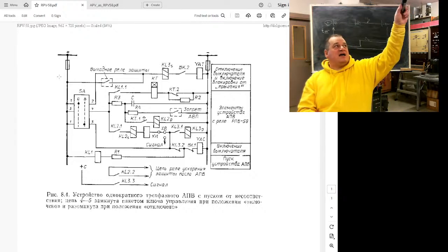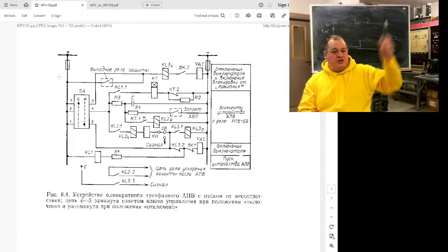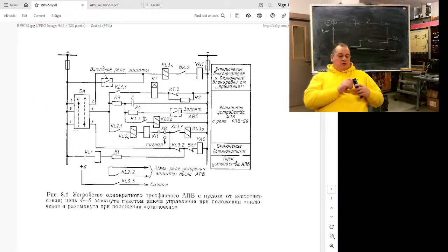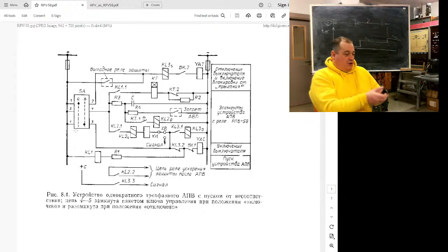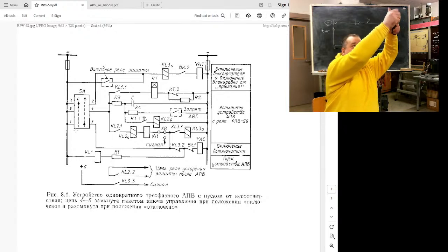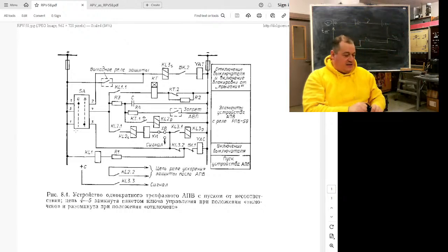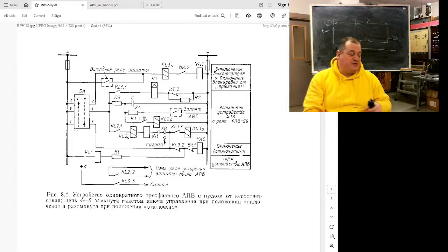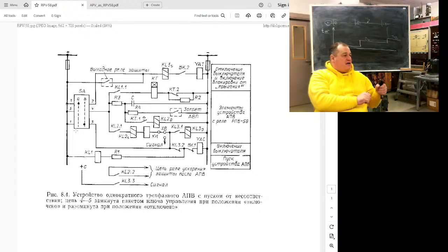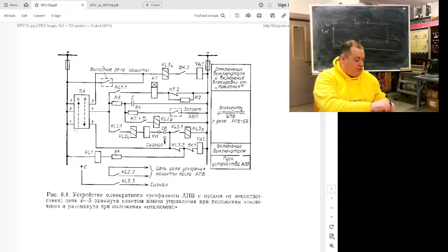This is not original. This is the second stage of the control switch. This block is the control switch, and control switches for this application are interesting. They have four positions: two locked and two spring loaded with release. It's done firstly as a safety measure. You cannot connect or disconnect the line without first putting the switch in the stable closed or open position. So this position, switch off, and only this will give a command.